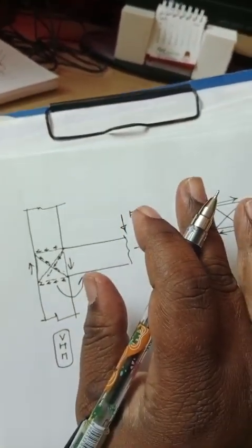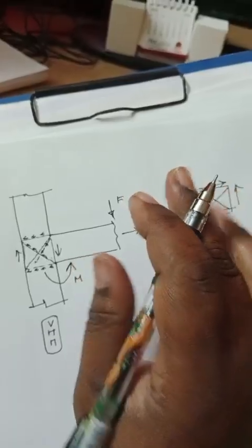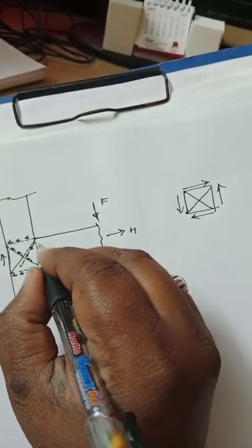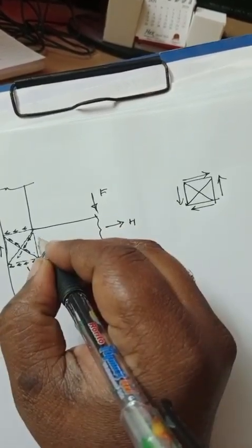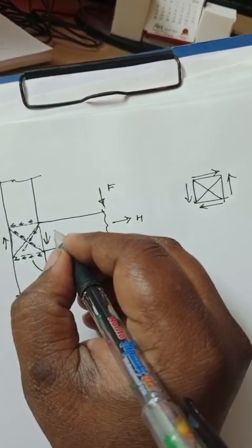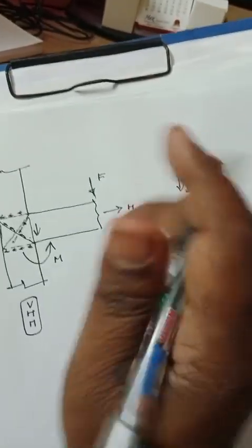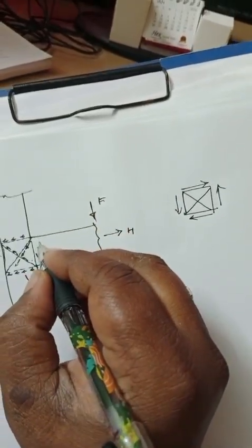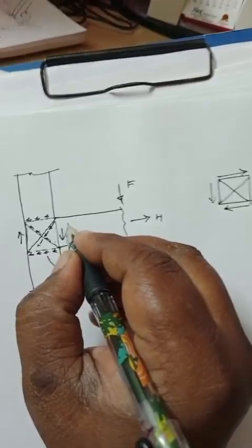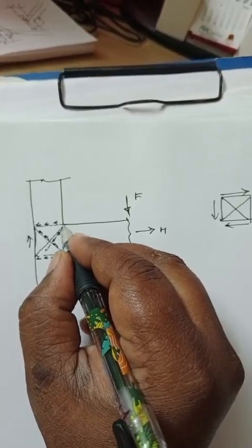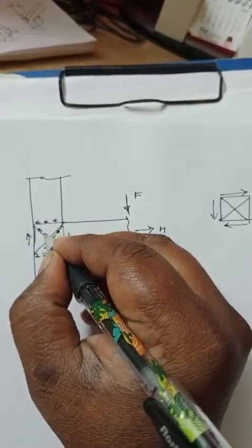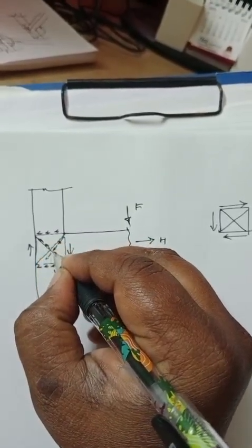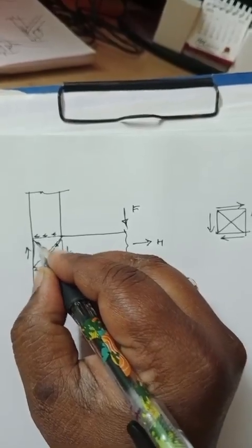Most likely what we do is provide the reinforcement which is supposed to cross the shear plane in the perpendicular direction. That is the ideal case, but it is not always possible. Ideal case in the sense we have to provide the reinforcement perpendicular to this plane. So this will be the perpendicular, and this will be the perpendicular to the other.